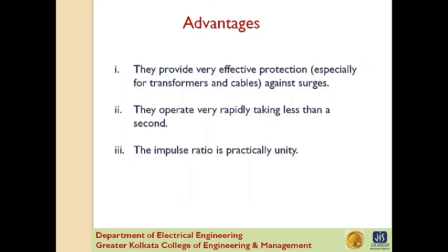Now, what are the advantages? They provide very effective protection against surges. They operate very rapidly, taking less than a second. The impulse ratio is practically unity. What is impulse ratio? Breakdown voltage under surge condition divided by breakdown voltage under low frequency condition.